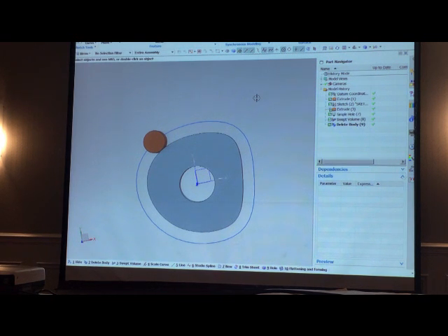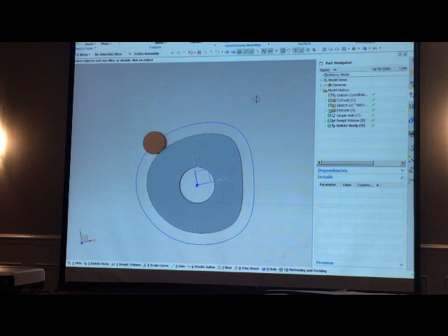And it's very, very hard to create the geometry represented by a high-speed formed piece of grinding stock on these shafts. So that's what held us up releasing this, because this is limited to either normal to the shaft or like this plate cam. In other words, you can't tip it at an angle. So what we've got is the Parasolid people working on a deal where they can do a lead and lag angle, like you do with a cutting tool, so that we can simulate this cutting wheel at this odd angle going around a shaft and cutting out the flute on a cutting tool or a drill bit. And so that's what we're waiting for.